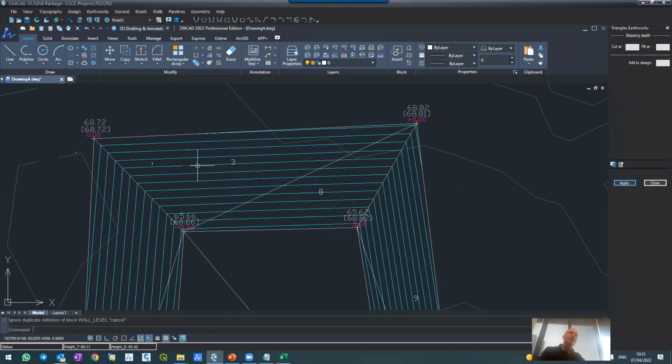But if, for example, inside this triangle in the existing surface there are 6 or 7 points that create, let's say, a small hill here, this triangle will not reflect it, because it's an interpolation of points 1, 2, and 3. So obviously this is inaccurate.